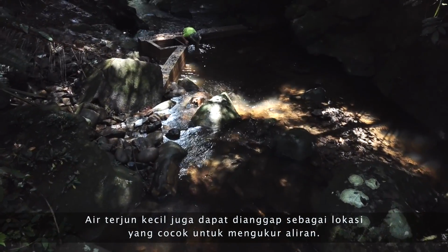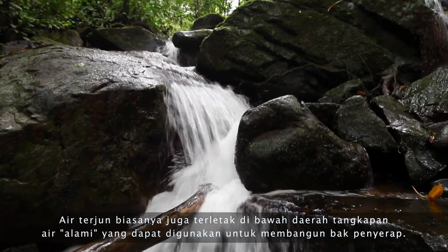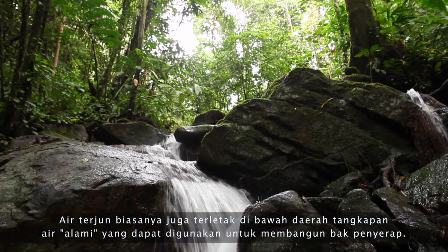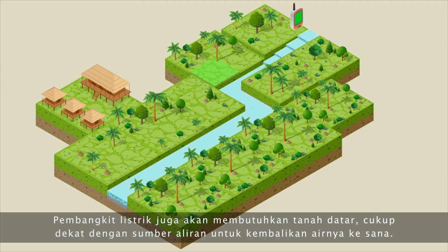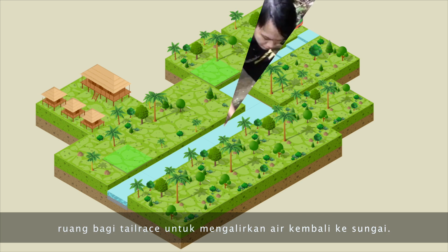Small waterfalls can also be considered as suitable sites to measure flow, and waterfalls are also normally located below natural water catchment areas that can be used to construct an intake. When considering a good site for the forebay, it is important to find a portion of flat ground not too far from the intake. The powerhouse will also require flat ground near enough to the stream source to allow room for the tail race to discharge water back to the stream.